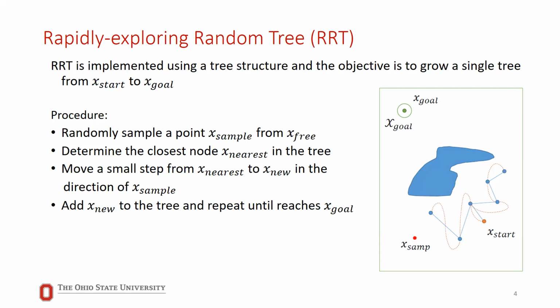So depending on the function you write for how you get that random node, it again finds the shortest and moves forward. So it's planning that. It might find a different direction from where it started, so it's like a tree, but it's saving the information. There is a shortest path between nodes, right? At the end, once the tree branch reaches the goal, the planner will say, this is the path that you can take, and it will take you from the initial state to your goal state.